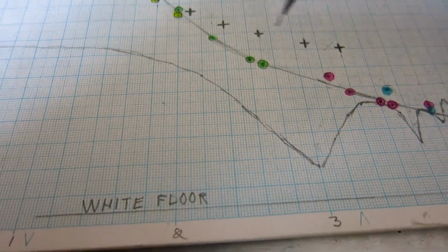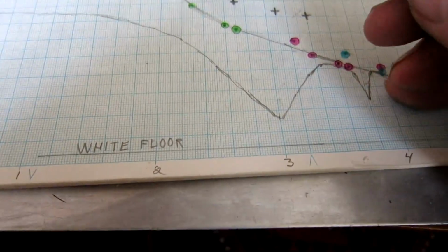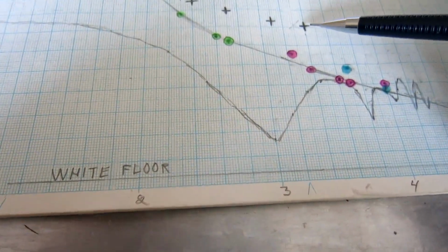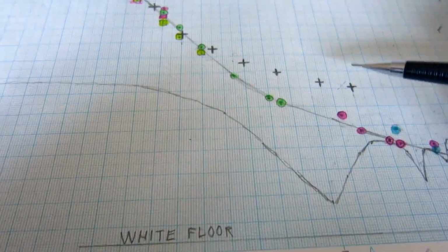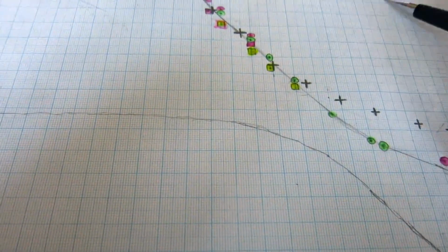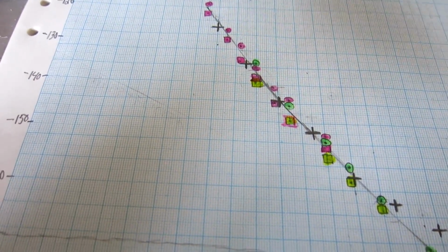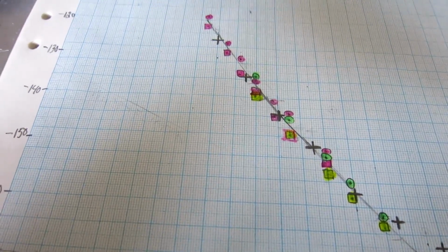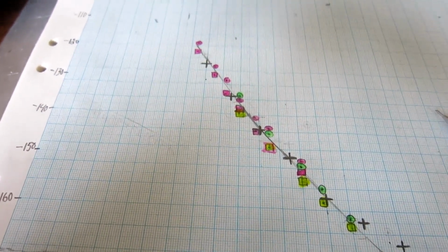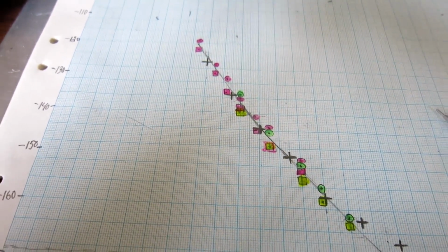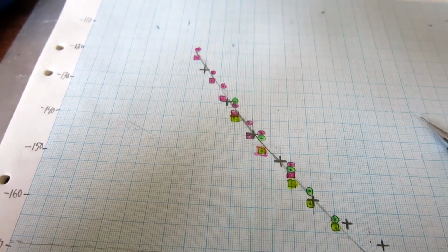So above 200 Hertz or so, the selectivity of the crystal filter gives a significant improvement to the noise of the Wenzel. But closer in, it seems that the selective amplifier now no longer adds any noise. And it will be interesting to give it feedback and see how it behaves as an oscillator. And that will be the next video.